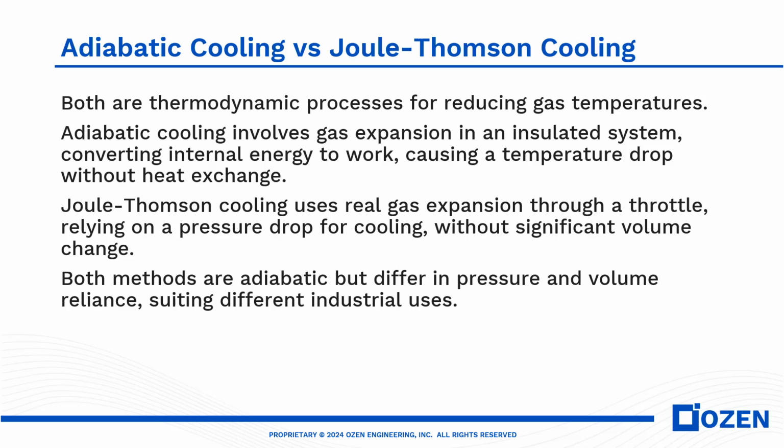But Joule-Thomson mostly relies on a sudden change in the temperature and the pressure, so it is not necessarily with a significant volume change. So although they are similar, they are different in the way that they drop the pressure.